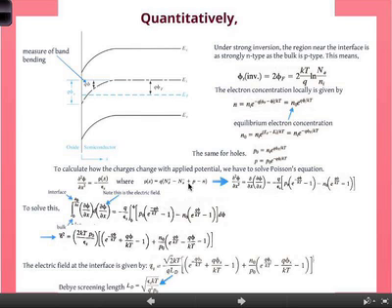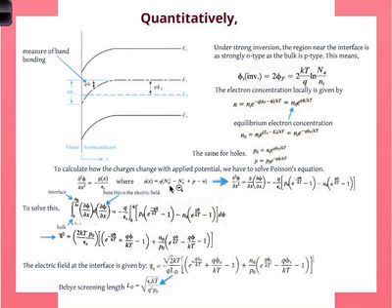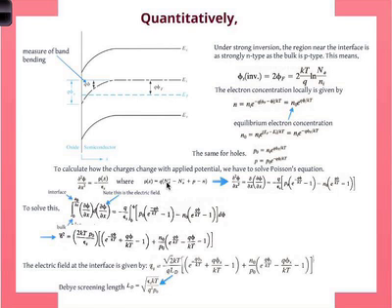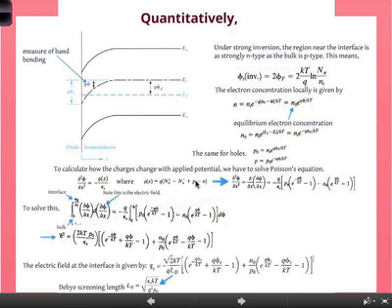And you can ignore the donors, ignore the acceptors if there are none. Here you can ignore the donors because it's p-type, and the acceptor concentration is equal to the equilibrium hole concentration. So you know these numbers; you plug those in, which is p_0 in this case, and the expressions for p and n come from here, which we just talked about. Plug everything in, and you have a relatively straightforward differential equation which relates the band to position, phi as a function of x.